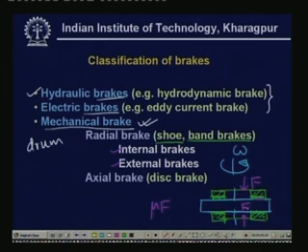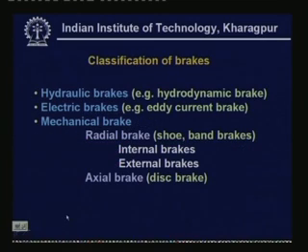You see that here the force is applied in the axial direction, whereas in the radial brake the forces were applied in the radial direction. So these are the two important differences between radial brakes and axial brakes. Now these are roughly the classifications of brakes, and in today's lecture we shall concentrate on the shoe brake, and in the next lecture we shall talk about the band brakes and disc brakes.